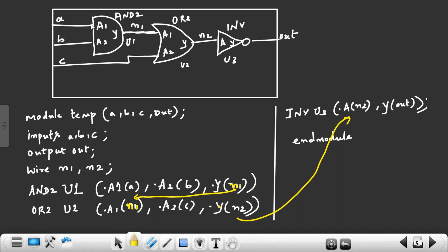So it is the number of independent inputs. See, this library name can be different also. It is library specific. The library designer is there, right? I told you the library characterization team is going to design the library file. They can give any name they want. They will not always use AND, they can use only AN. AN2, they can give. Any name they can give. I've taken just an example.